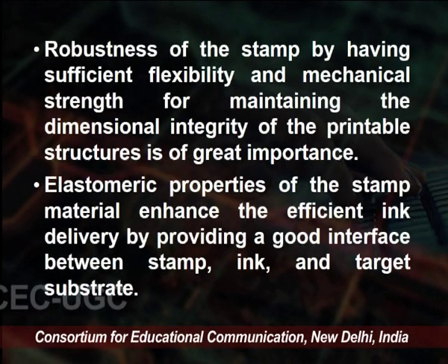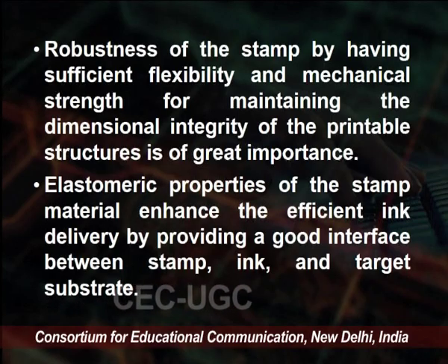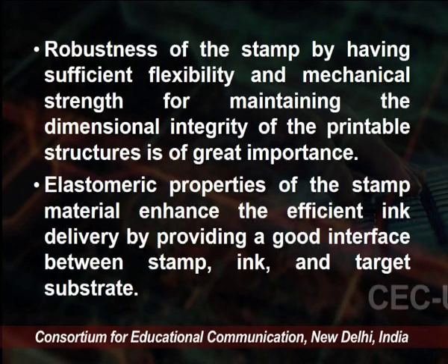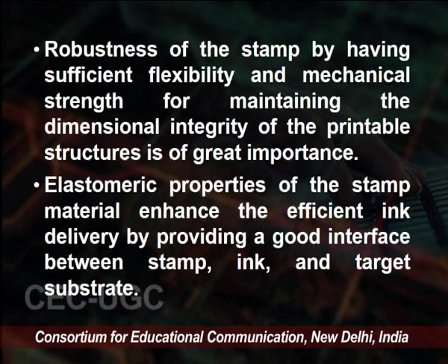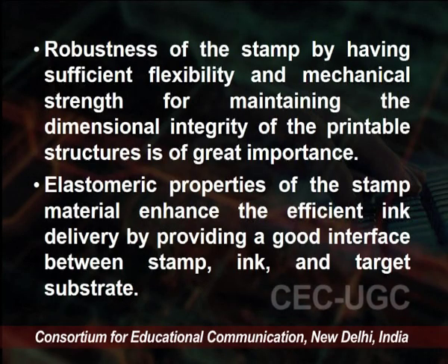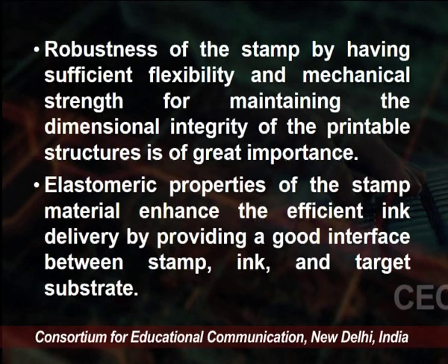Robustness of the stamp, by having sufficient flexibility and mechanical strength for maintaining the dimensional integrity of the printable structure, is of great importance. So we choose PDMS so that we can have good flexibility as well as good mechanical strength.